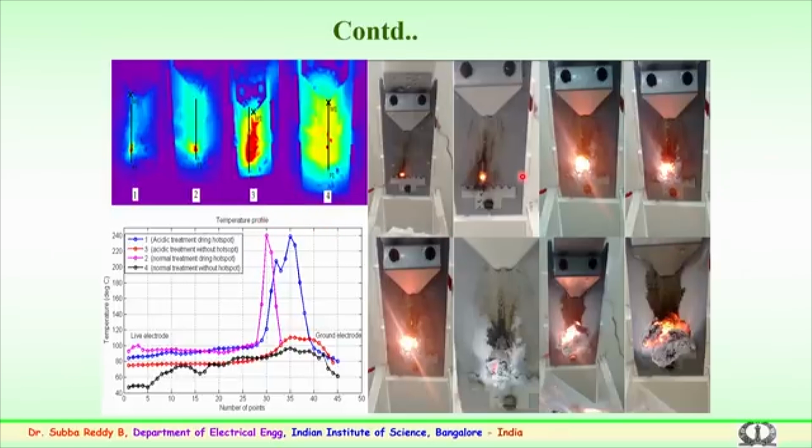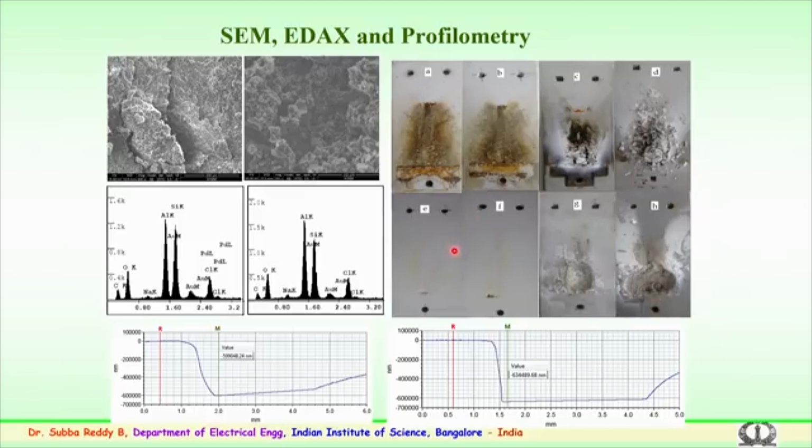You can see how the surface degrades over the period of time during the experimentation, wherein the surface erodes and the entire sample becomes punctured. This happens again depending upon the solution. Here both normal conditions and acidic conditions have been studied for the high temperature vulcanized rubber and also the silicone rubber, that is the liquid silicone rubber. This type of phenomenon was noticed, wherein a lot of erosion and puncture of the samples occurred.